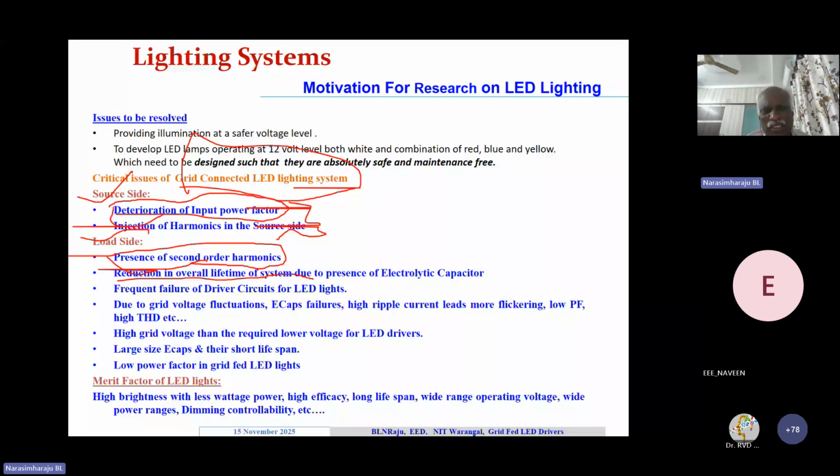and the lifespan is very short, if you compare to thin film capacitors, which provide a much better life. High lifespan, even with the size of these capacitors which can be used in these LED drivers. In very good quality drivers, normally they do use those thin film capacitors, of a very small size, but they provide a good lifespan also. So these are the various issues,